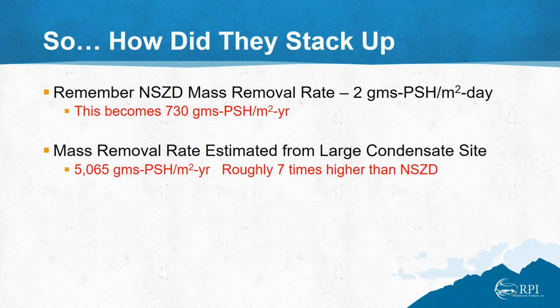So from these numbers, it's clear that activated carbon, and BOS200 in particular, has a role to play on these sites. And we all know there's a difference between diesel and gasoline sites. Diesel doesn't really have a groundwater issue, so it makes a lot of sense to move into natural source zone depletion. But the temporal component to those cleanups, they're not short, they're very long. So clearly we can accelerate that removal, the cleanup of the site, with the use of the activated carbon, the BOS200. The carbon is acting as a platform to support the biological activity.